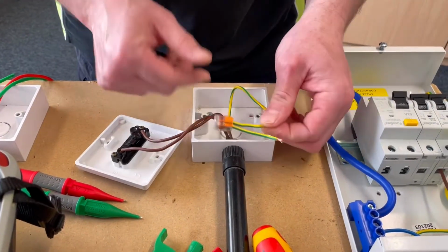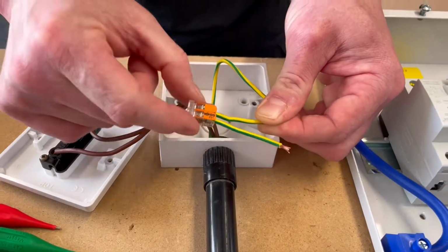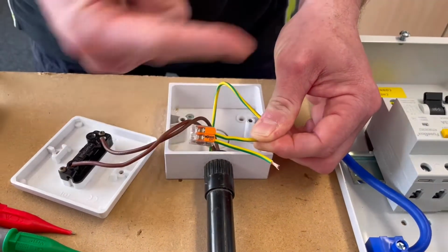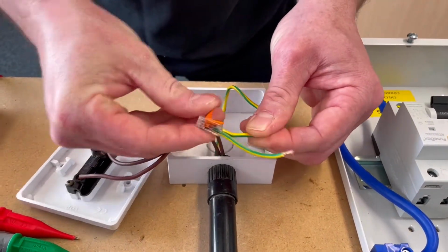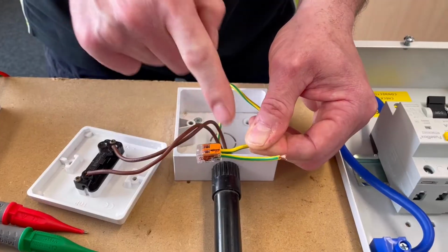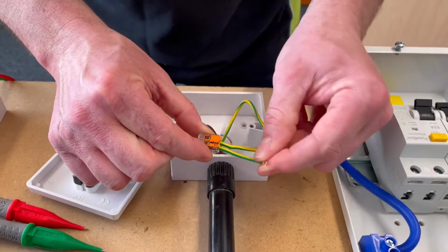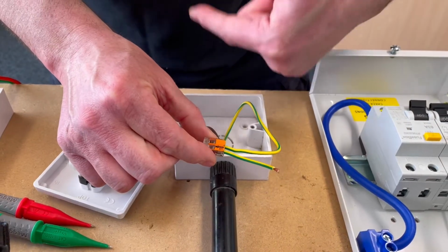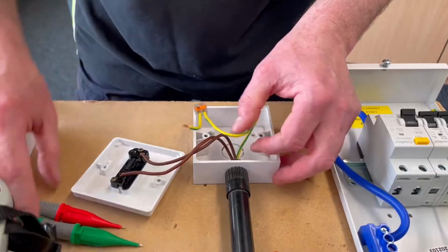So I've made this little 221 Wago connector with an extra link on it so we can make the test. And this here will be used in later videos to extend the circuit. So of course people are saying, why didn't you just go on that end? I could do, but I've used the Wago 221 and I've put an extra little link on it so I can use it in the future to extend the CPC as we create the circuit that goes on to do office number 2 and office number 3. So at the minute I need to prove the CPC gets down here.